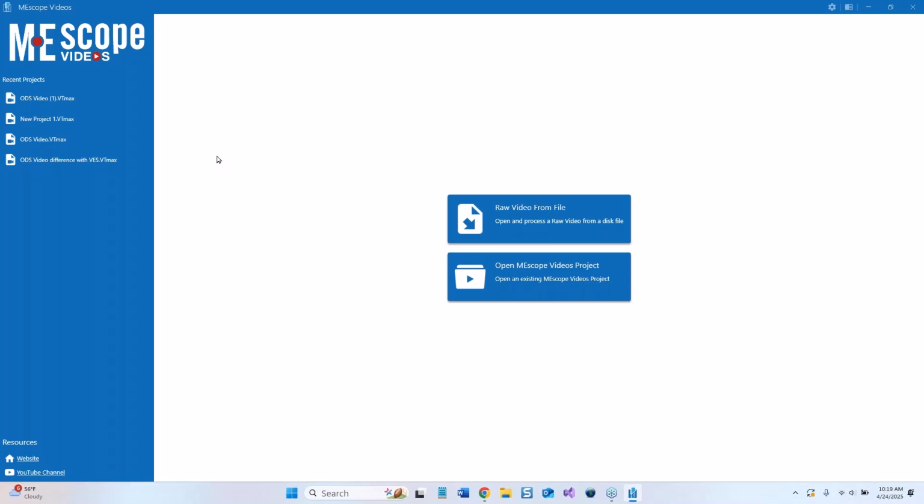When you lay out a modal test or an ODS test with accelerometers, you can use FEA mode shapes, you can do a lot of different things, or the customer just says, hey, I've got a problem with this machine. And so you put a couple of accelerometers on the motor and a couple on the pump and maybe a couple on the gearbox, and you can see what's going on based on that accelerometer data. But with a video, you're going to see everything in the field of view, and you may see things moving that you weren't even thinking about. So that's the advantage of the video.